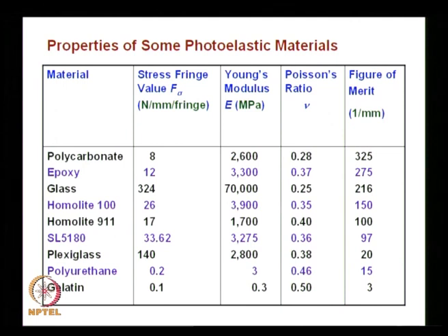So, this gives you an idea of what are the various photoelastic materials, and what we have seen in the class today was we looked at the importance of color code. We said the color code sequence is advantageous to calibrate the polariscope, to find out the maximum or minimum principal stress direction, and also to find out the sign of the boundary stresses. We have looked at the nail test, we have also looked at how to find out the sign by an external member. Then we moved on to model to prototype relations.